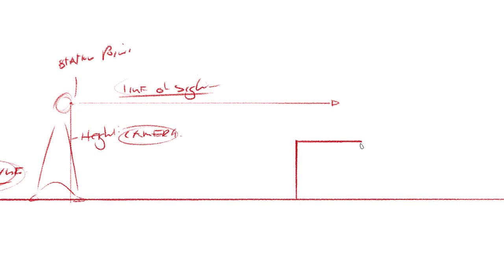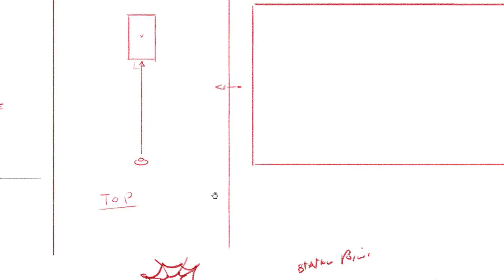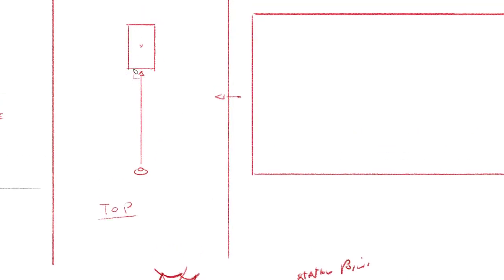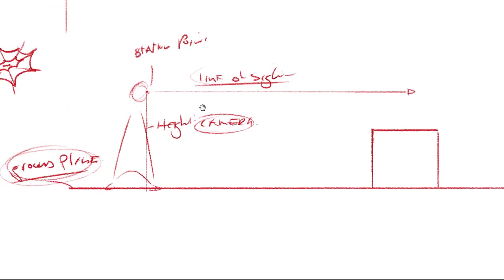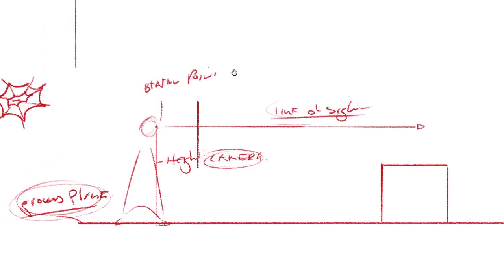box. Okay, so in top view you can see it's a little bit longer, so the front is a little bit narrower. And he's looking through a picture plane. Right. So let me just quickly move this a little bit out of the way. Okay, so the picture plane is also very important, because this is where perspective drawing is happening actually.